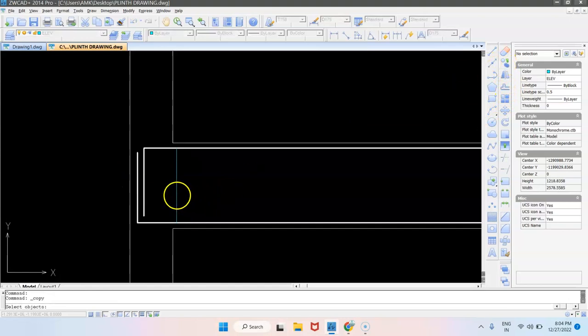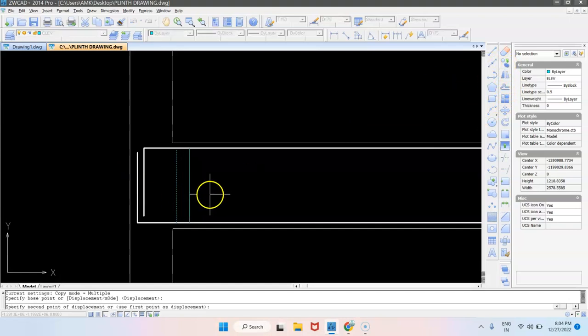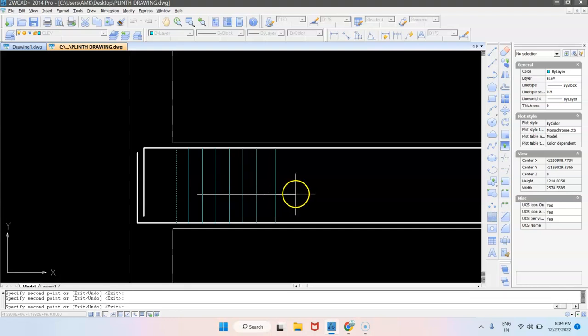And if you look at the stirrups, they will be closely spaced near the support because the stirrups are important from the point of resisting shear. And then as you go away from the support, they will be much more widely spaced.